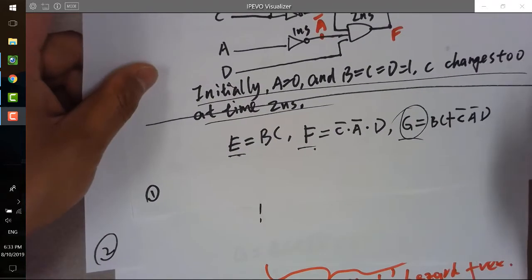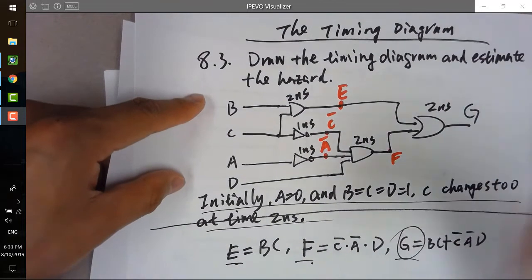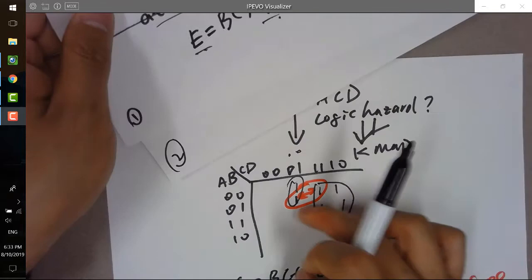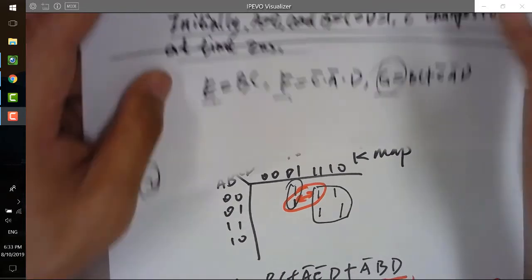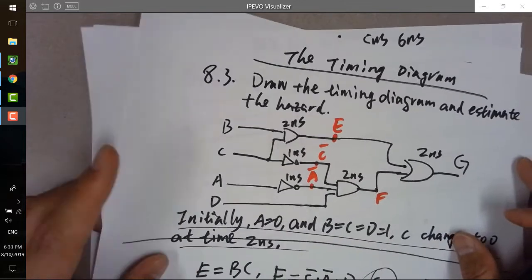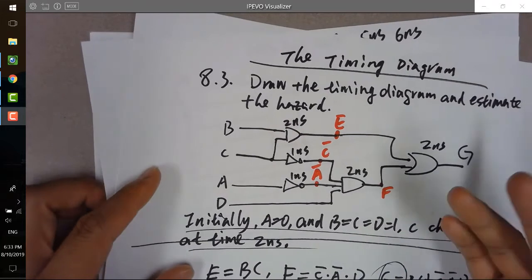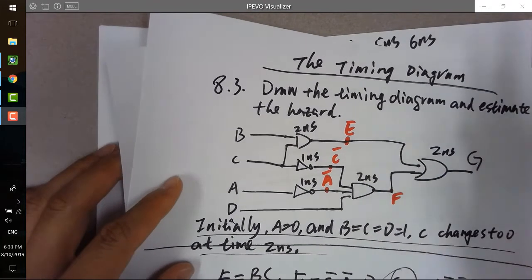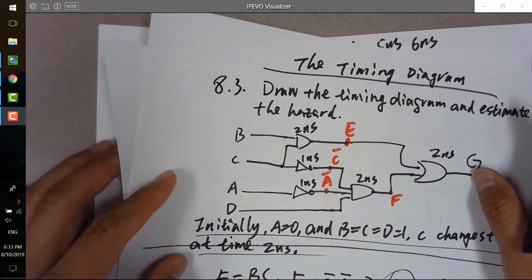design a digital circuit like that. If you see a digital circuit like that, actually you can find out the static 1 hazard by converting it into a K-map, and you find it out, you fix it, you redesign the circuit, you modify that. So keep in mind, if you can see a circuit, you can actually identify the hazard and fix it, and recover and add something to it, make a perfect circuit without any static 1 hazard.